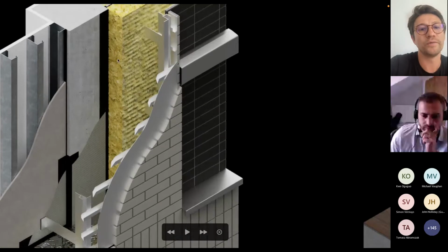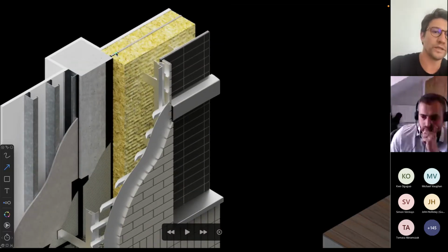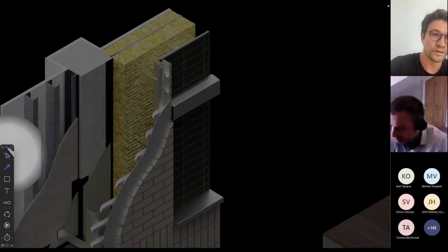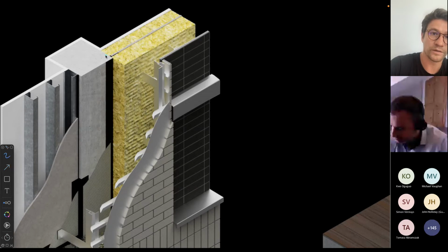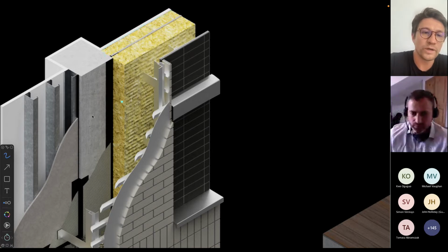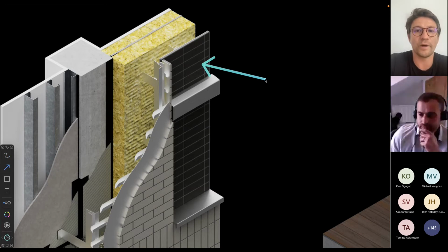So I would assume that the sheeting board with EPDM would be the ultimate seal for the building, and the vapor control layer would be here as a normal rain screen assembly. So brick slips is effectively a rain screen, the way I see it.